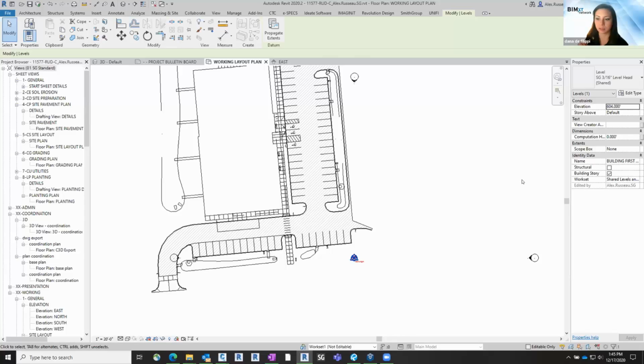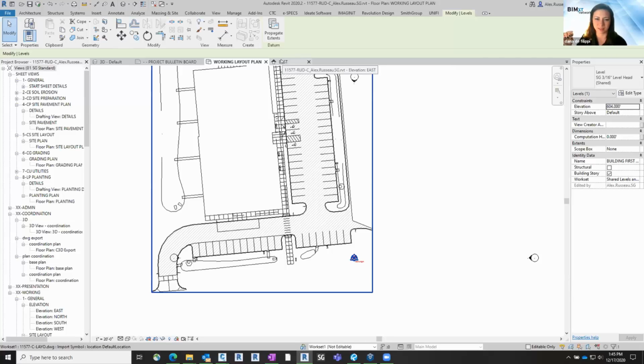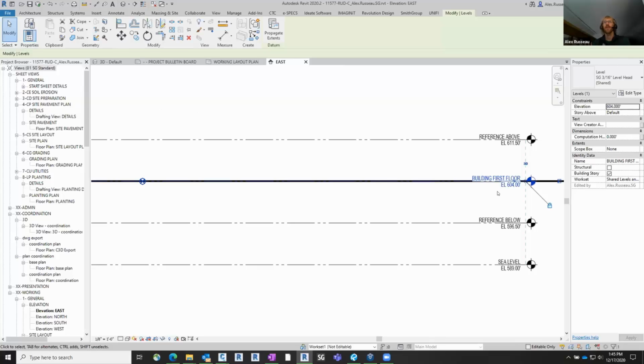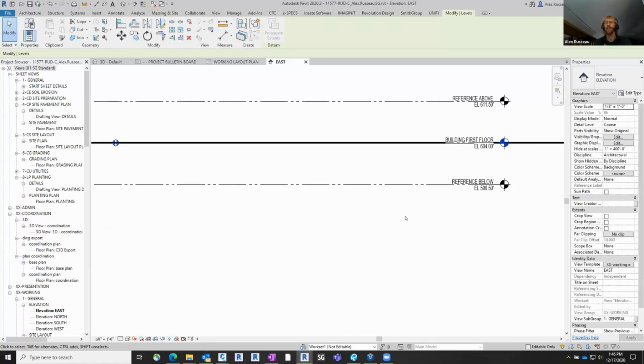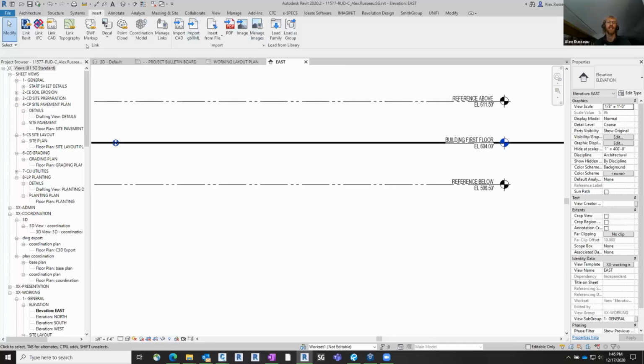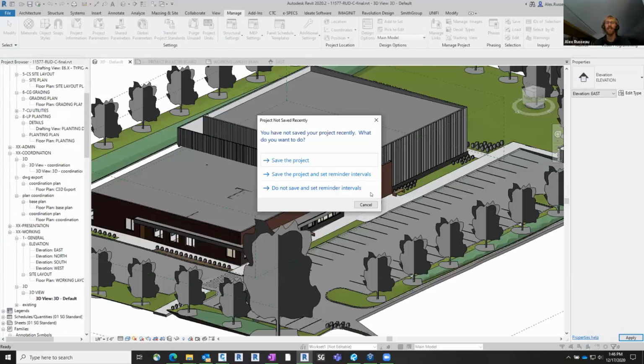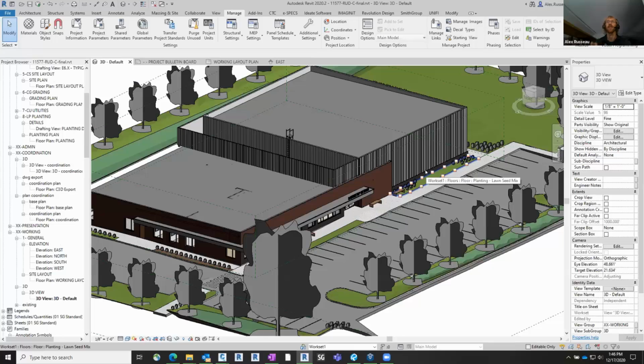And Heather asks, it looked like before you relocated your project using the position tool, your sea level was set to negative 15 feet. Is that just the way our template is? Yeah, that's just the way our template's set up because our building floor is where I really want the building to come in. So I had that initially set at 0. The step that I do next, after I have that first floor set, is I bring this down to 0. And then I do all of my modeling off a survey point or the sea level. So in this model, I end up setting all my floors and everything to sea level so I can type in true elevations to get it all set up.